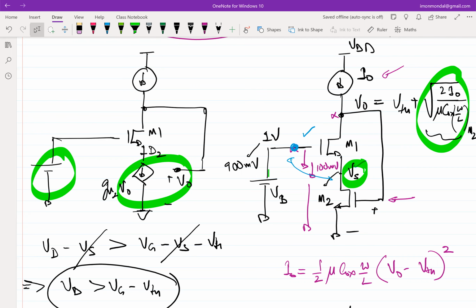If you go back to your initial assignments of GDS versus VDS and so on, you'll see that the resistance of M2 is going to 0. Now, resistance of M2 going to 0 means this feedback doesn't exist, right? So even when M2 gets into linear, your feedback kind of doesn't exist, because this feedback exists only when M2 is in saturation.